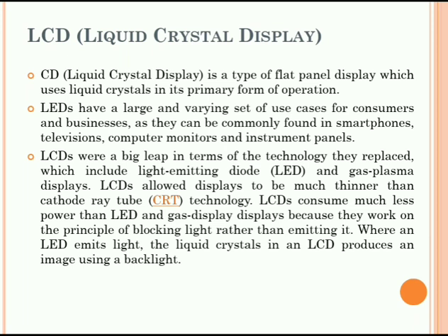A liquid crystal display consists of two substrates that form a top and bottom cell that contains the liquid crystal mixture. The inside surfaces of the cell are coated with a polymer that is buffed to align the molecules of liquid crystal. The liquid crystal molecules align on the surface in the direction of the buffing. For twisted nematic devices, the two surfaces are buffed orthogonal to one another, forming a 90-degree twist from one surface to the other surface. This helical structure has the ability to control the light.